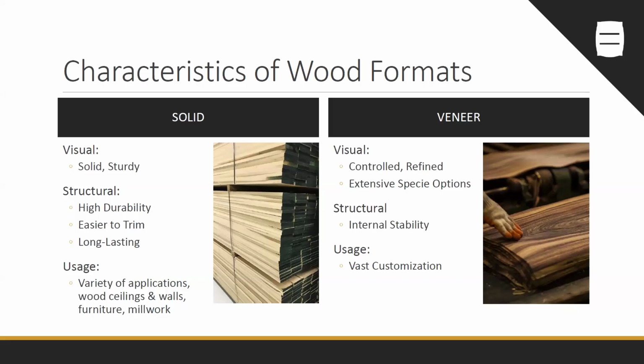Solid wood is also hygroscopic. So what this means is it absorbs and desorbs water. As humidity fluctuates in an area, wood can shrink and swell inside the space. For this reason, and again, we'll talk about it shortly when we get to systems, we may require dowels on some panel grill depths or thicknesses just to ensure that the blades remain straight over the life of the project.